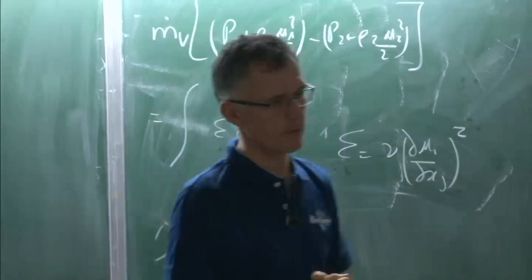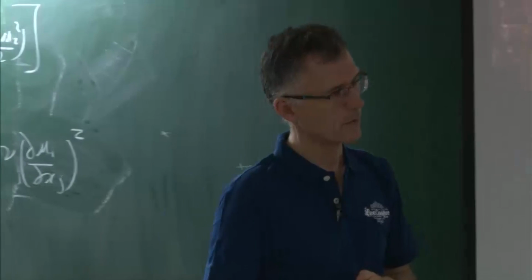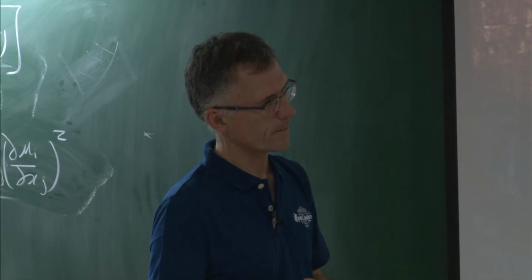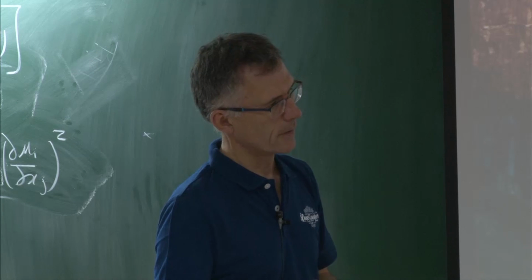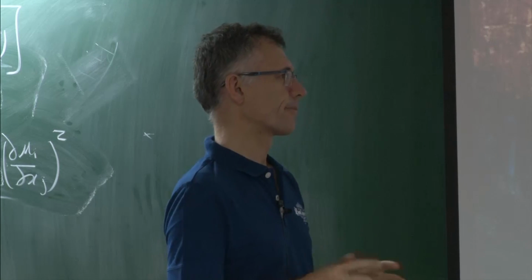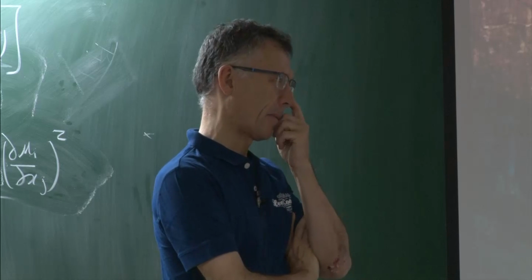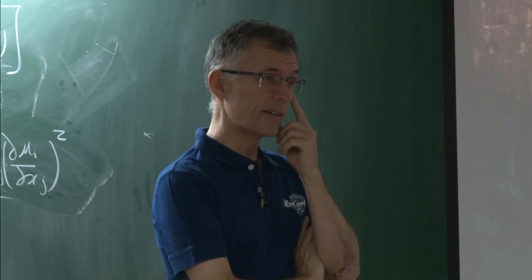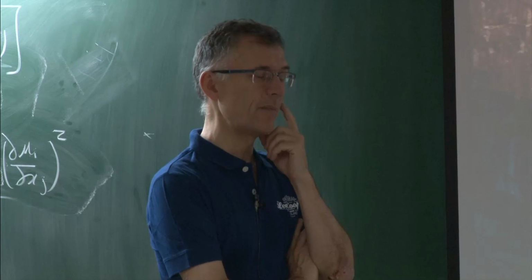So this Smagorinsky subgrid model is known to have issues near the wall. There's one other subgrid scale model, WALE, that they claim to be good near the wall. Have you ever tried that? No, we like the subgrid scale model to have a limited effect.